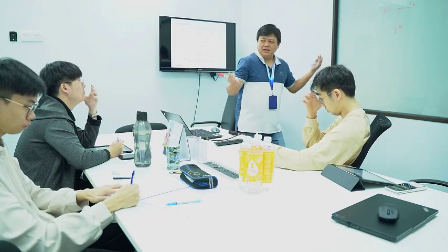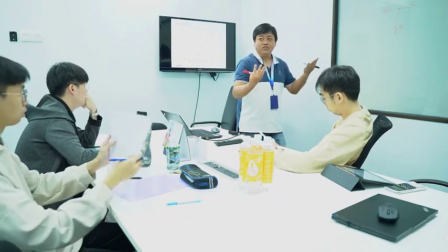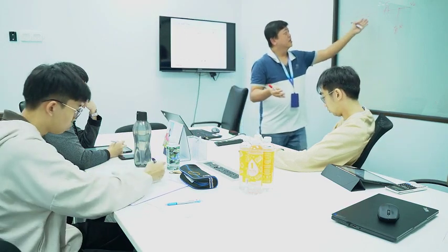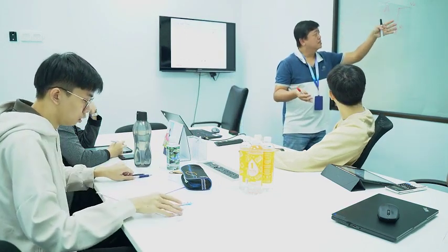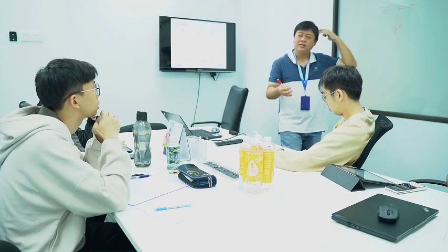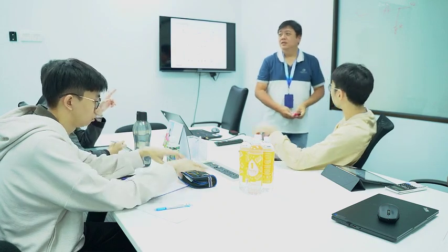A very quick way of understanding, by intuition, is why this guy passes high frequency signal. Look at this diagram, just by thinking. For a capacitor, when a high frequency signal passes through it, it will behave like a short circuit.